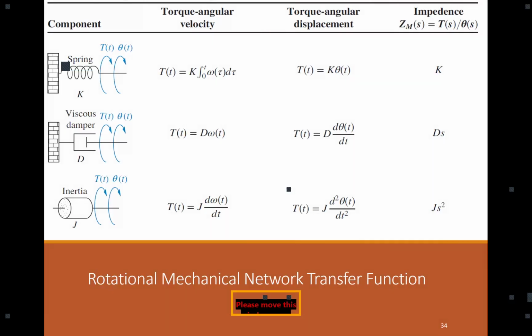By the way, when you design a control system, for example for a robot, when you have the x over input, you normally have more poles, for example a pole at zero. When we talk about that later, a pole at zero creates a marginal stability problem.